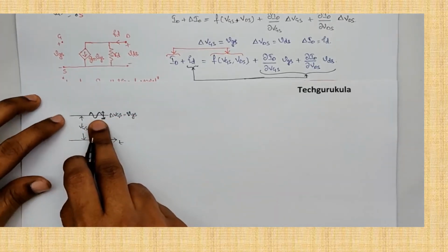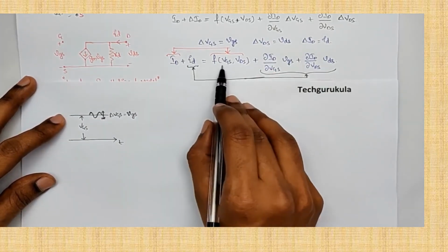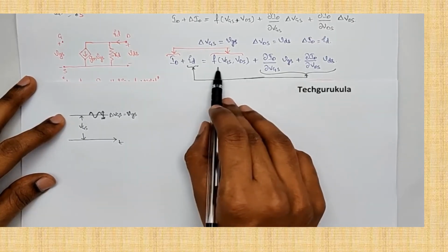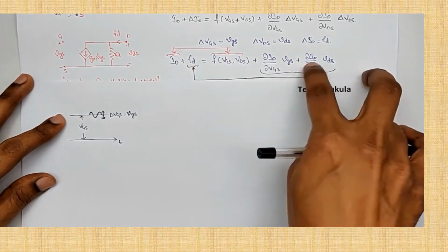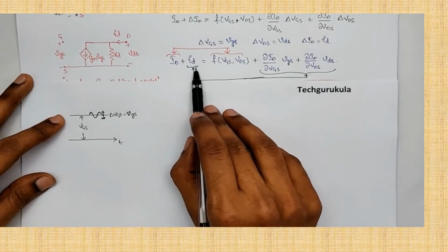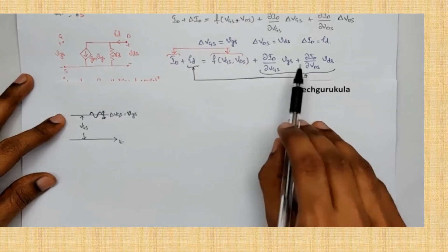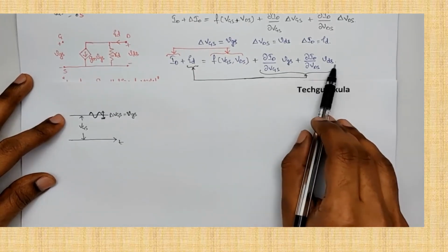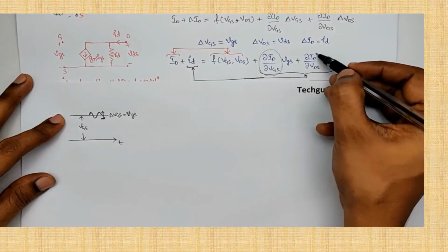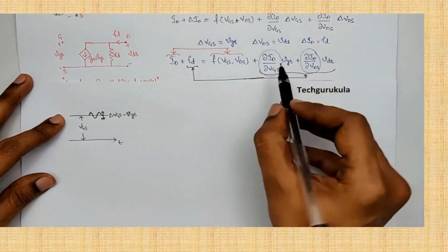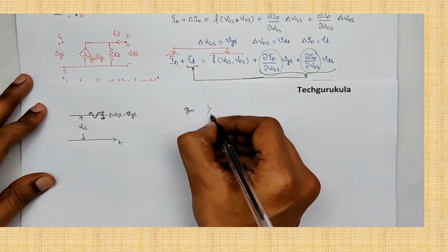Now in that case, when we did the Taylor series expansion, we got that the DC current was equated to a function which is dependent only on the DC values. So the DC was completely not dependent on the small signal values here. But when you see the small signal current that resulted because of the changes in the voltages here, that was depending only on the small signal values, small VGS and small VDS. But of course, there were parameters like delta ID over delta VGS and delta ID over delta VDS. These are the two key parameters which we defined as GM and 1 over RD.